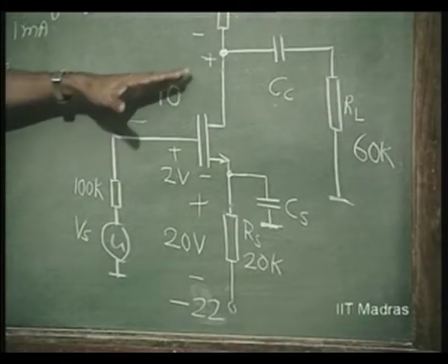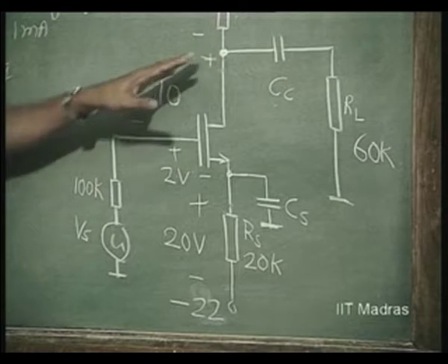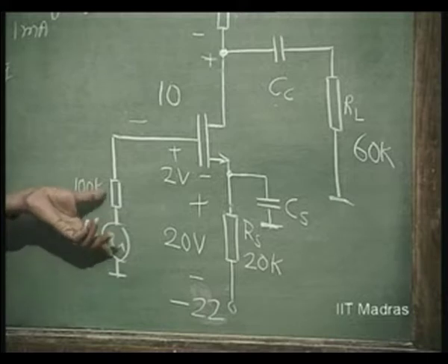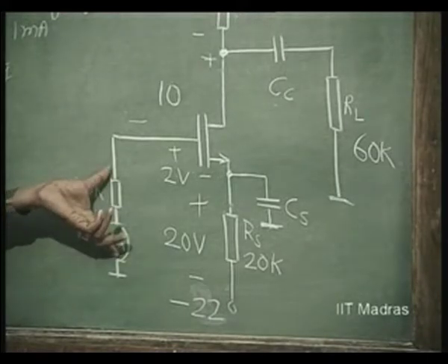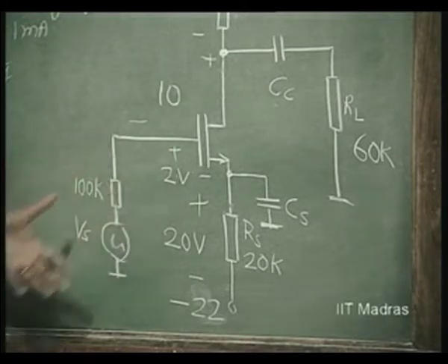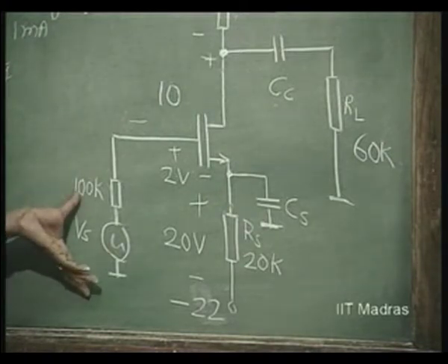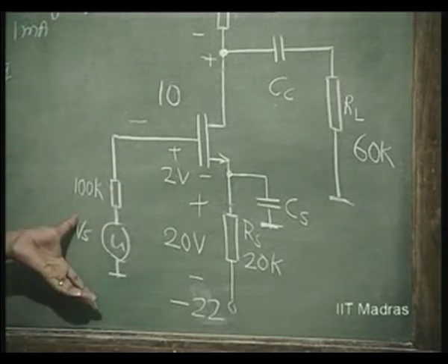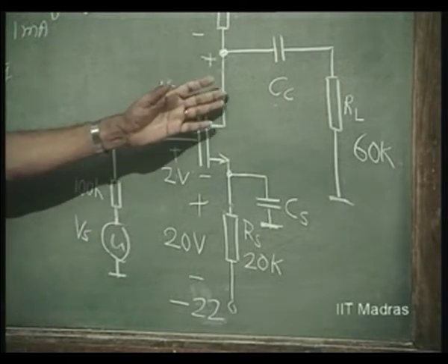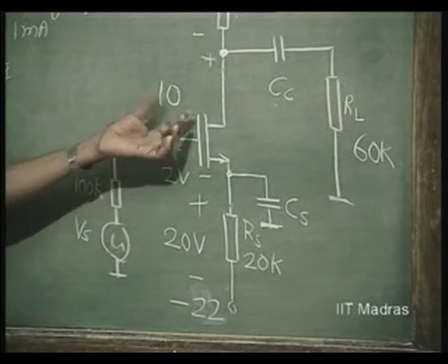Now, this is under the assumption that this side it can go up to 0 volts, but it can actually go up to 1 volt. That means on one side there is a swing of 1 volt extra given. That is because we do not know that there is going to be some swing here, it is not going to remain constant. When this goes down, this will go up. So definitely we are going to give some amount of leeway for this voltage to increase here, so that it will definitely be less than 11 volts. Is this clear? So it is not going to be full 10 volts, it is going to be strictly speaking 11 volts on one side, but since this voltage is going to increase, it will reduce the swing.